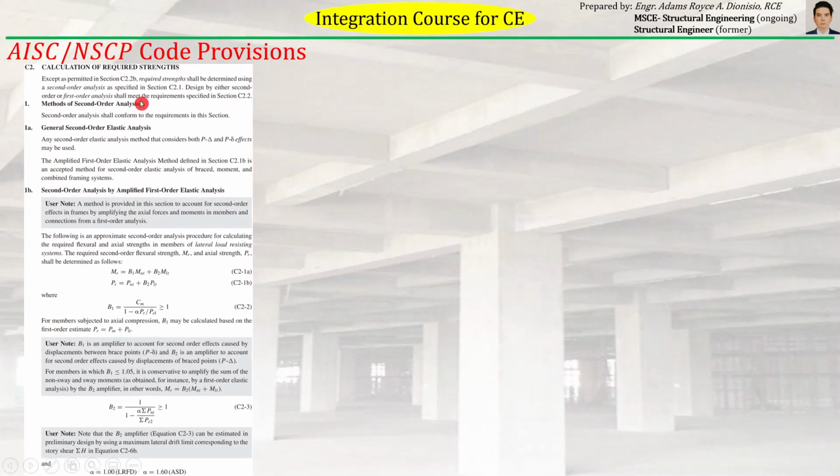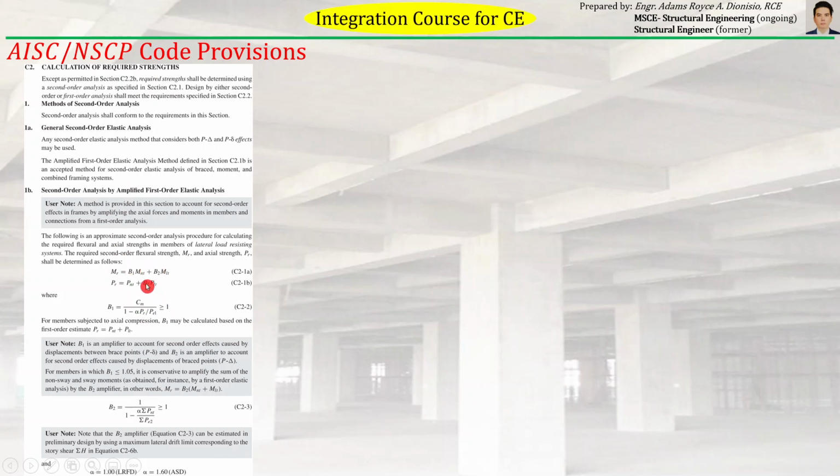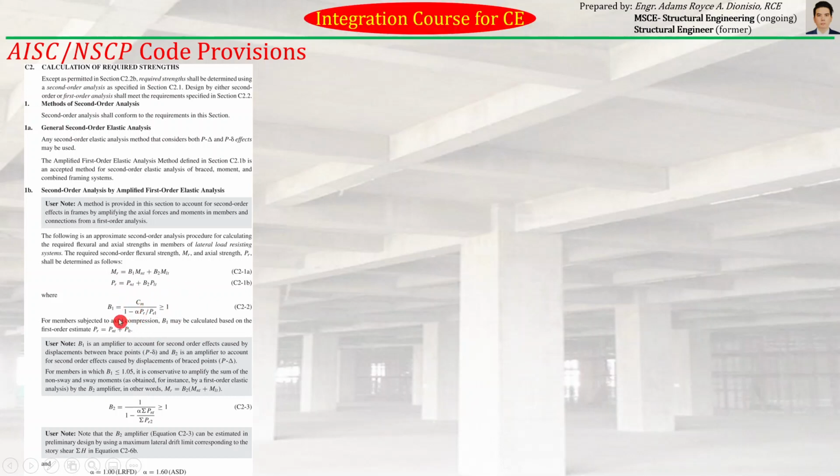And then ito, additional code provisions related to analysis and design of members. Yung mga requirement for second order effects. So ito na nga, ito na rin yung pinakita ko kanina, yung mga formulas. M is equal to B1 Mnt plus B2 Mlt. So dito na rin siya makikita. Formula for B1 is equal to Cm over 1 minus alpha.